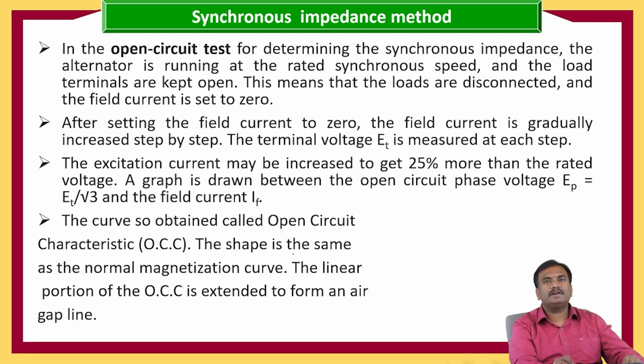The shape is the same as the normal magnetization curve. The linear portion of the open circuit characteristics is extended to form an air gap line.